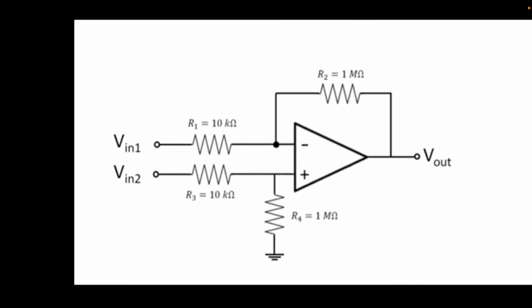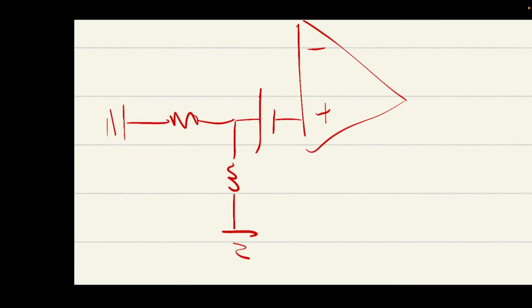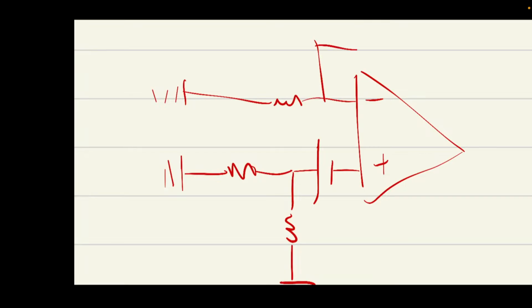One key thing about doing this calculation is these input voltages will be grounded, because what we're using is superposition, and with superposition we're only considering one supply at a time. So these input voltages will be grounded, and we'll consider that in our sketch. So that's what I've done here. This is VN2, but it's grounded, and then same with VN1, it's grounded as well.